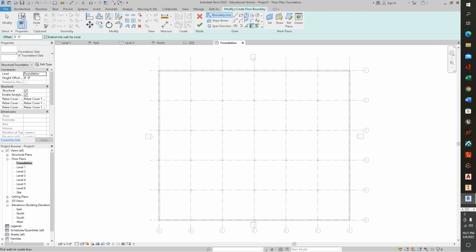You'll notice there's the options. We could put all kinds of different shapes in here, draw whatever. What we'll just do is pick walls. We've got these walls up here, and we can use the pick walls function to pick the walls that we've just set in there, and we'll go around on the inside of the walls and click on the inside of the walls as much as we possibly can here, and they'll all turn pink, and that's great. And then we press finish.